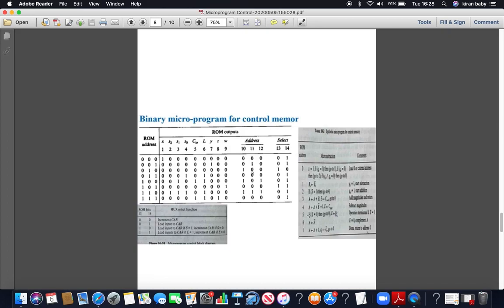So what you have to do is perform a 2's complement, and also do a clear bit. Okay, so that is being performed here. That particular operation is represented in binary format here, and the address that needs to be loaded is 101, and the mux line is 01. Whenever the mux line is 01, you have to load the input to the CAR. So what was present in that address line? 101. That 101 address needs to be loaded to the CAR.